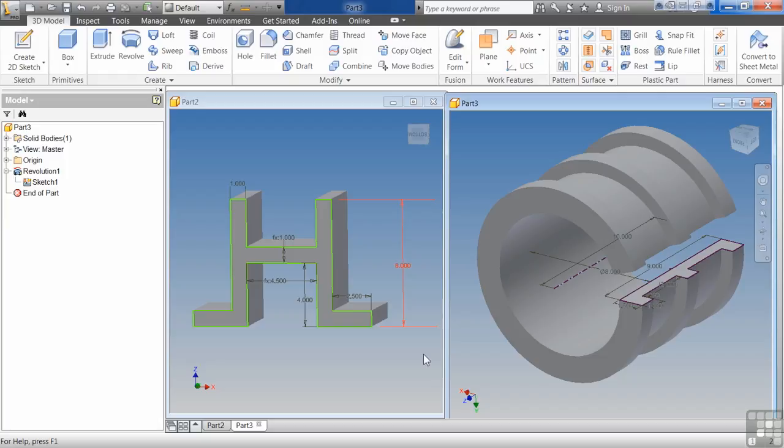What that means is it's going to be the first thing you have in that part, so you're going to start up a sketch, draw something out, and then either revolve or extrude it. It has to have that unconsumed sketch, meaning no other object is using it. If something else is using that sketch, then it's no longer the base feature anyways, so it's not that important.